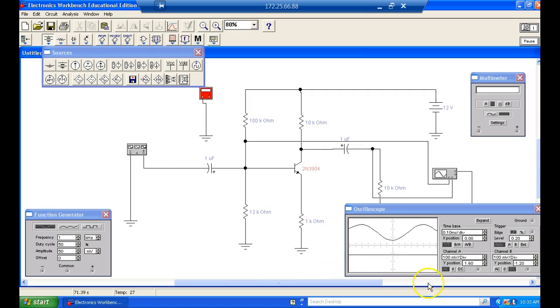So I don't know if the simulation, the bias measures okay, except when I go right here, this bias is all messed up. So when the guy did this, he didn't do something quite right. I don't know what's going on here, because if this is shorted, all your emitter current is going this way, and if all your emitter current goes this way, then that means what?